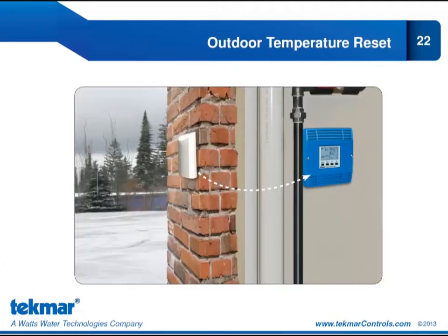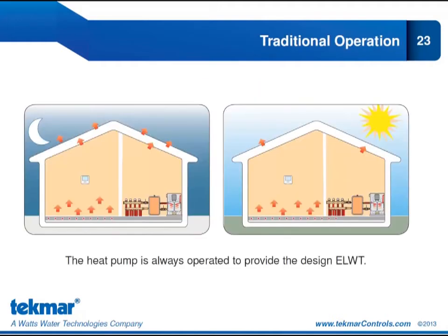So outdoor temperature reset is a term that probably most of you have heard of in terms of boilers. Virtually all boiler controls now have the outdoor temperature reset feature, and we're going to look at how it can apply to an optimized geothermal heat pump system. First, we'll go over the traditional operation, and then look at how an outdoor reset control can make a positive impact on the efficiency of the geothermal heat pump system.